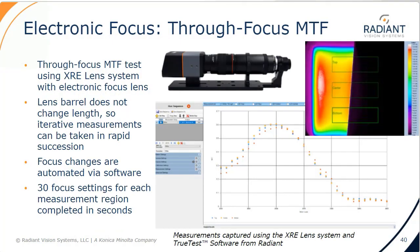Electronic focus also enables effective through-focus MTF analysis. Using image analysis functions, connected measurement software can iterate through the focal settings of the electronic lens until best focus is found for each analysis region in the measurement image. Since the pupil position of the optical system doesn't need to be adjusted for each focus setting, the through-focus MTF analysis can be run completely autonomously without any intervention from the user or the operator. A complete through-focus MTF test can be done in a matter of seconds.